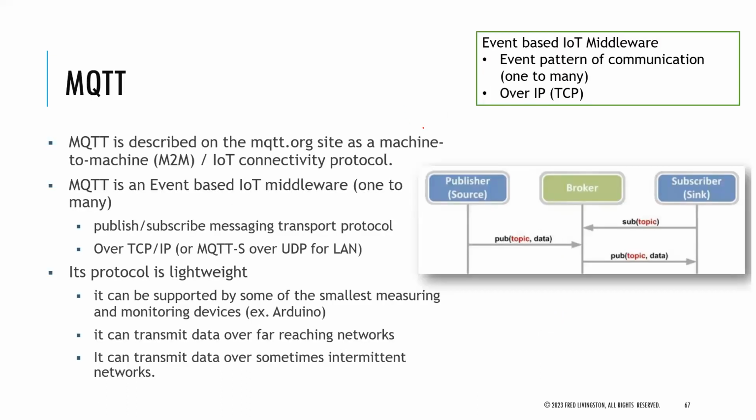And with MQTT, we can actually connect to multiple sources. We have a broker in the middle. So just know how these things work. We have your clients, they are all connecting to this broker, and they can be passing messages back and forth. But I'm able to communicate with more than one person using this broker system than I can with Modbus. It's more of a client and server system.